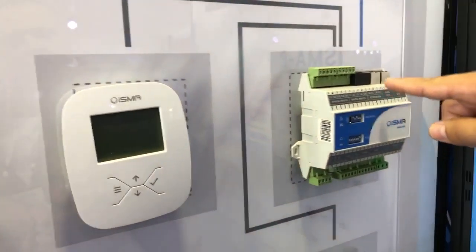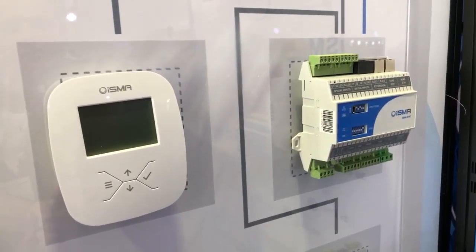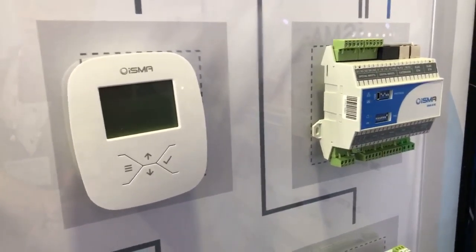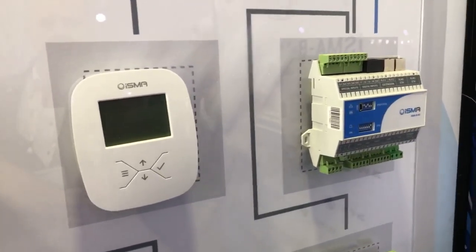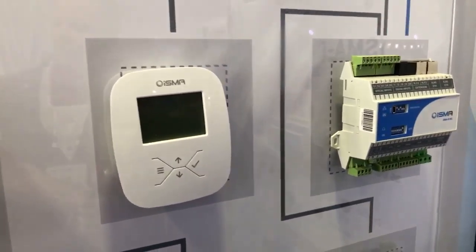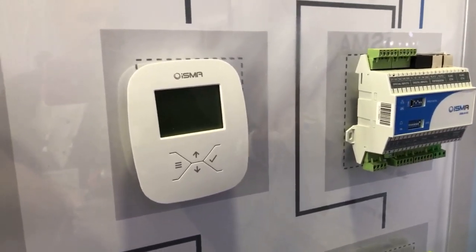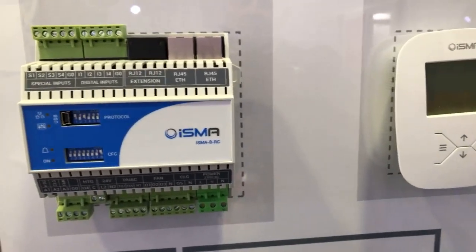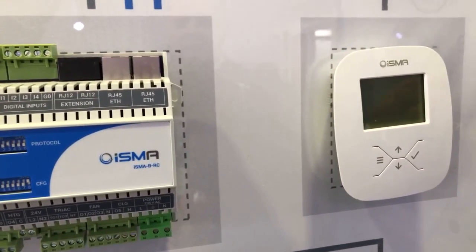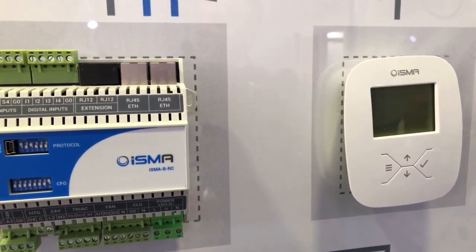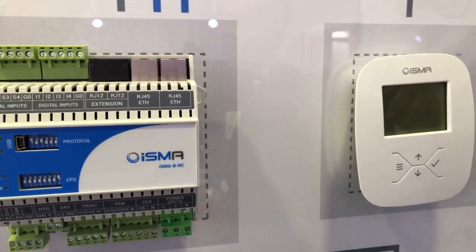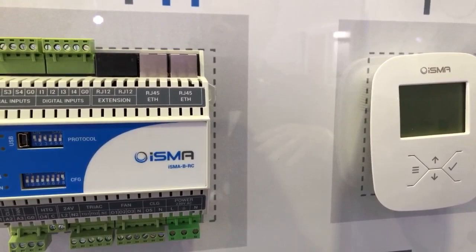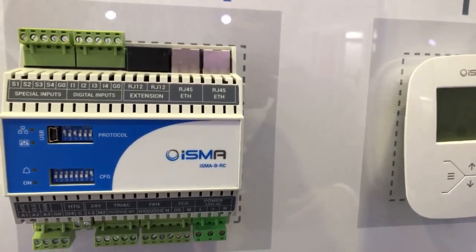This controller is going to be available at the end of Q3, beginning of Q4. This is a new IP controller, designed for use in a fan coil unit or small application. We call it Edge. The microcontroller is going to be driven by a new Edge framework, ready for IoT connectivity. This is our display panel with a multi-sensor built in. It comes with a few different options: just a temperature sensor, or temperature, humidity, and CO2. It's Modbus and BACnet. Our whole portfolio is built around Modbus and BACnet, so every single device you can buy from us is automatically Modbus and BACnet enabled.